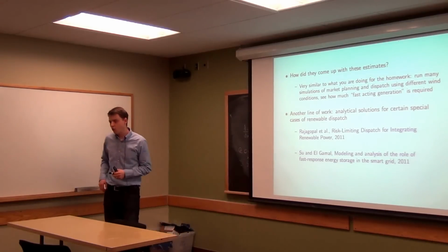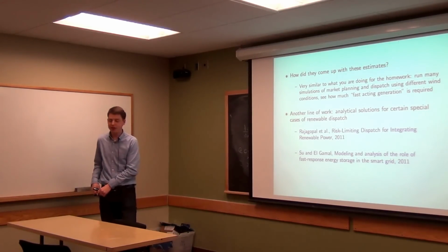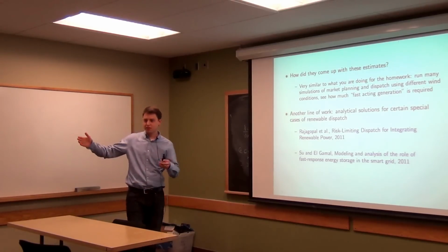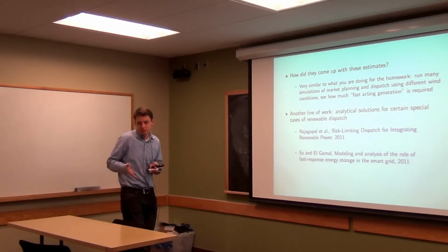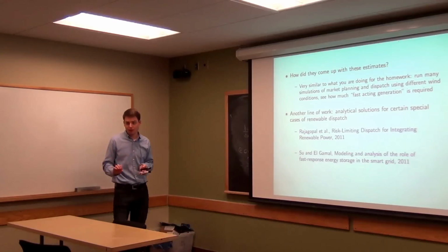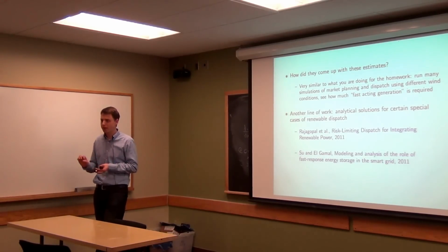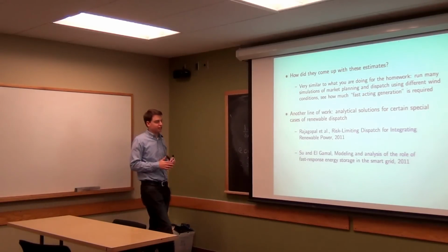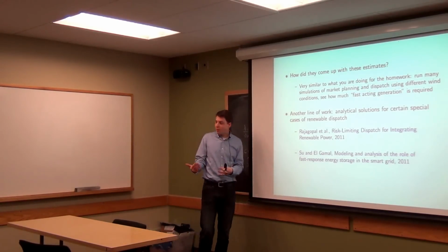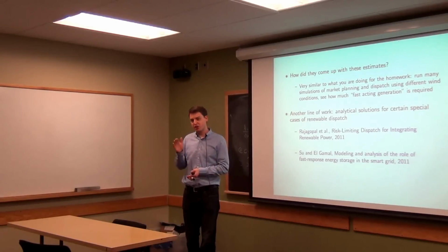There is another line of work that's a little bit different from this. We've been taking this model predictive control type approach, which is essentially saying, okay, I'm going to make predictions, and optimize based on that, but it's not an optimal approach, right? That's the first thing I said: this is not the actual optimal strategy, it's something that works well in practice. In the general case, general stochastic optimal control is very hard. So a parallel line of work has been focusing on cases where there might be simplifications, but where we actually can solve that stochastic optimal control problem exactly.